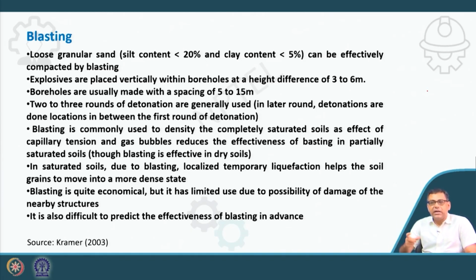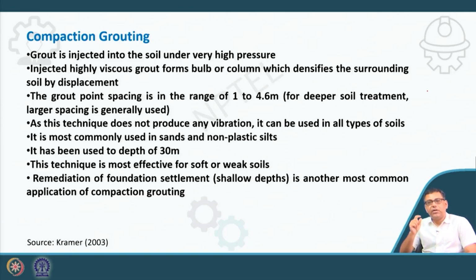So that's why you have to check it. You have to do blasting for 2 to 3 rounds, because first you do a round and check the compaction, or the performance of the blasting. Then you go for another round, and if required, one more round. Clear?